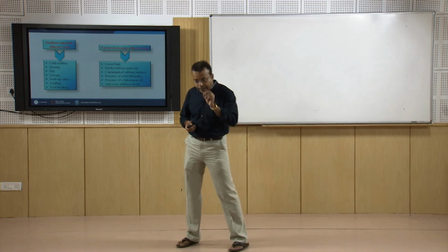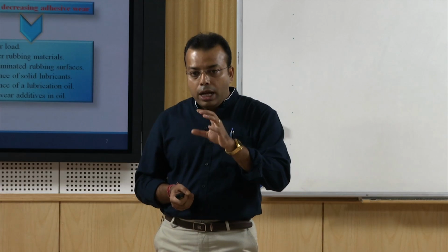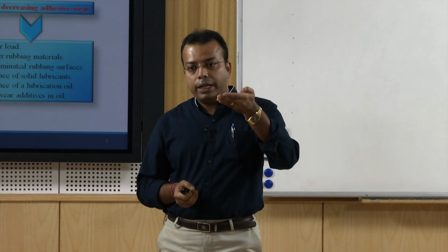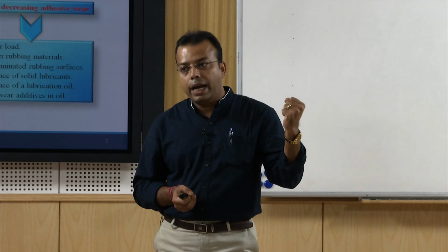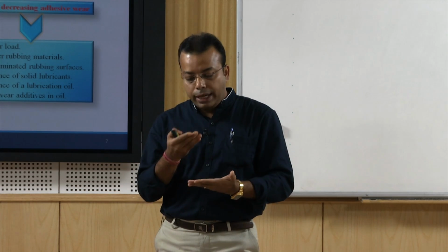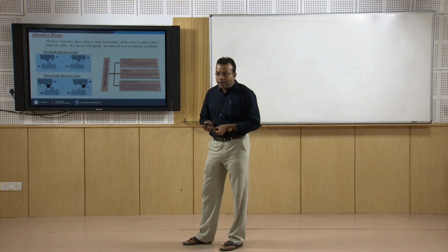So, you can use certain kinds of nanoparticles or nanofillers inside the oil, so that when the temperature keeps increasing, they will automatically absorb the heat at that particular interface, so that the friction will be less. Next is called the abrasive wear.